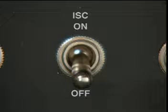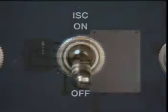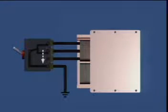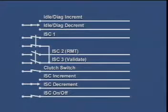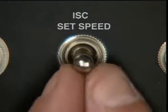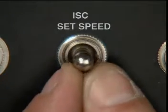An intermediate speed switch can be mounted on a cab panel for operator access. A 3-position switch can be used if 2 intermediate speeds are desired with ISC validation. When ISC speed 3 is required, ISC validation cannot be used. This 3-position switch cannot be used to activate all 3 ISC speeds. Systems using 3 ISC speeds require an additional switch or switches.